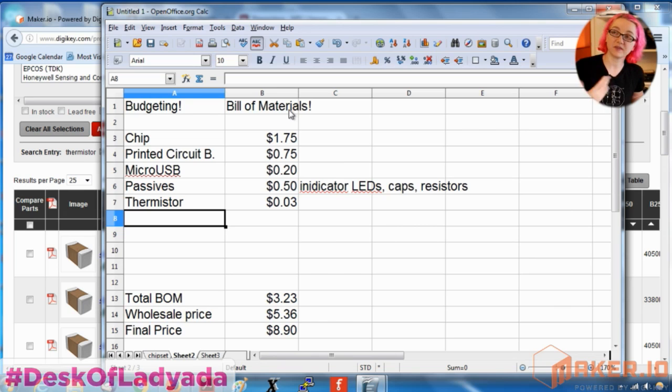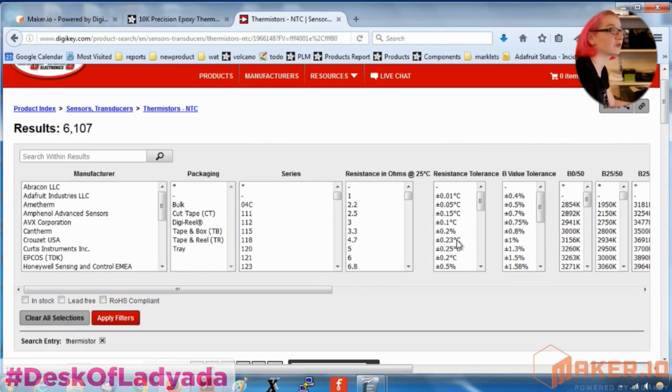Some microcontrollers don't have analog, like the ESP8266. It's a really great Wi-Fi chip, but it has one analog input, and it has 1 volt max, and it's kind of nice to have multiple analog inputs to do all sorts of sensing. So, okay, I got a thermistor. And that's like the cheapest sensor you can possibly get. And then I was like, okay, well, I want a light sensor because light sensors are very easy to use and are also low cost.